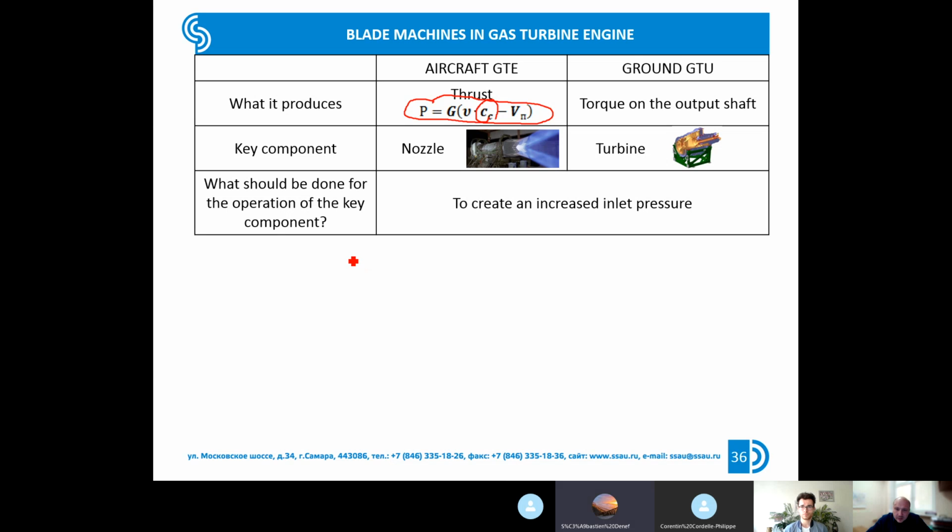The compressor? No, guys. You need to use a nozzle. You need to use a conical nozzle, a Laval nozzle. It doesn't matter. So to create a high-speed jet, you need to use a nozzle. But if you find a nozzle, it will not provide a high-speed jet by itself. You need to make some additional requirements. You need to provide the pressure difference between the inlet and the outlet of the nozzle.